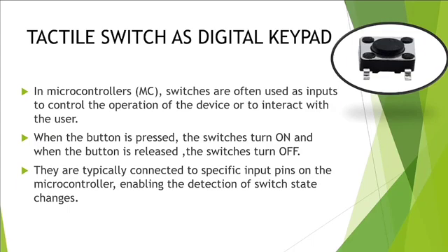Now coming on tactile switch as digital keypad. Switches are used to turn the power on or off. Switches are often used as input to control the operation of the device. When the button is pressed, the switch turns on, and when the button is released, the switch turns off. They are typically connected to a specific input pin on the microcontroller, enabling the detection of the switch state change.